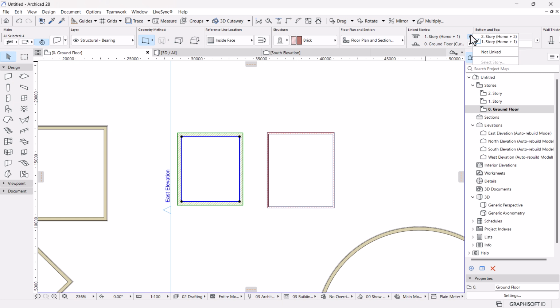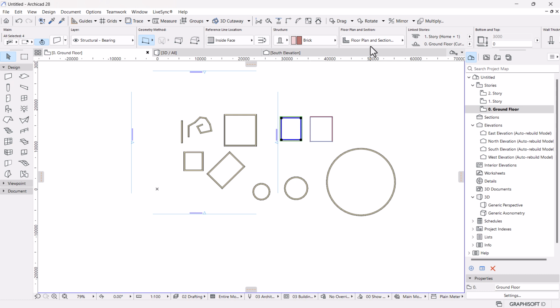If it's a multiple story building and you want this wall to go all the way to the 5th floor, you can run it all the way. It depends on your design. So it's very, very important to understand this. And then the bottom offset dimensions are also very important. If it's on ground, it will be keyed at 0 because the offset height is dependent on that level.